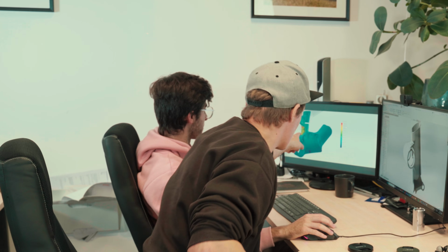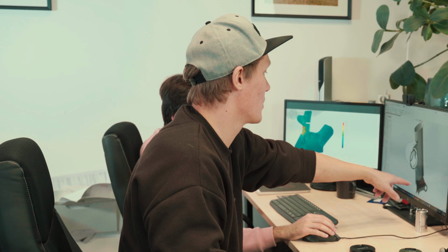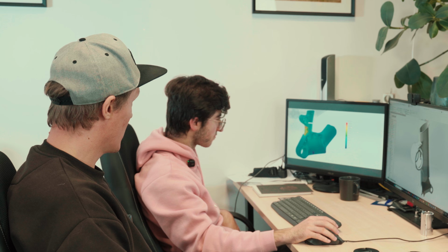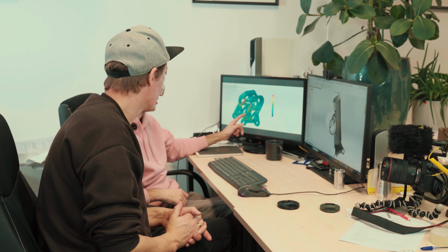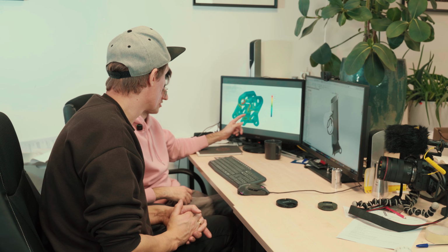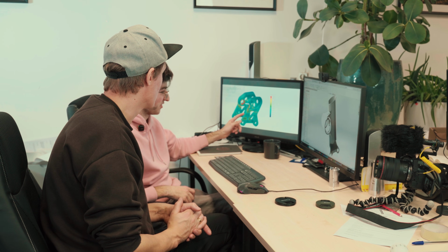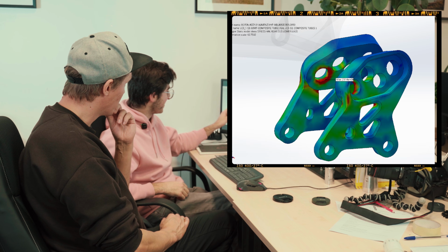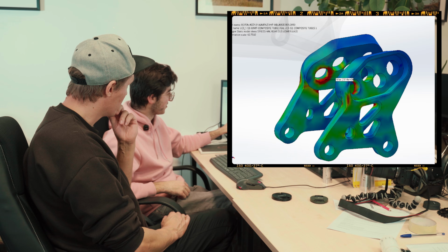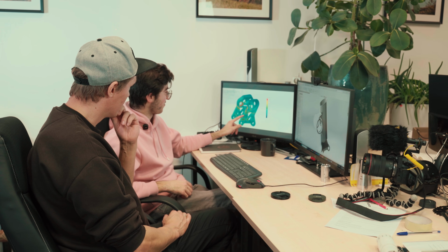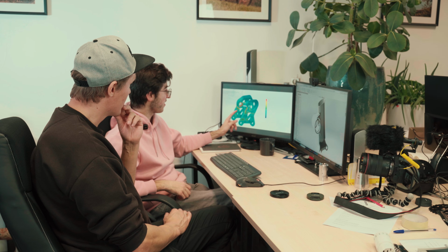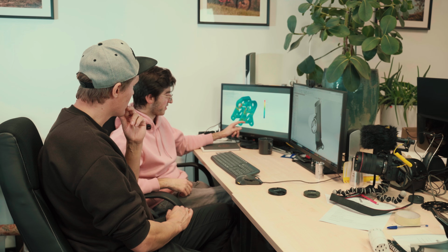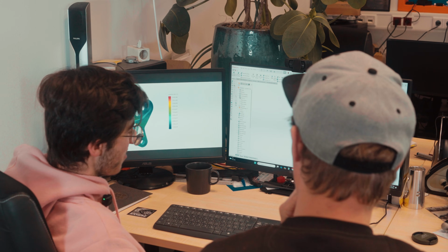Okay, and here you see in this load case it is red as well, but this solution is addressing the same problem, so we didn't have to make adjustments for this load case. The shock mount was pretty interesting because we just ran it in the simulation, but it was just a concept. The design wasn't finalized at all, but as you can see here we have some red, so that means that in this area we need to add more material. But in this area, it's pretty blue, so the material is not working in these areas. It means that we can remove some material.